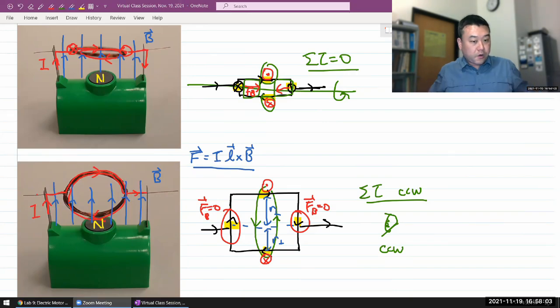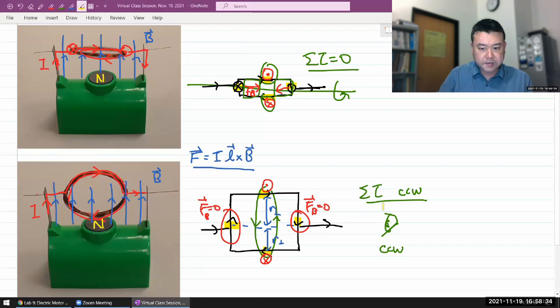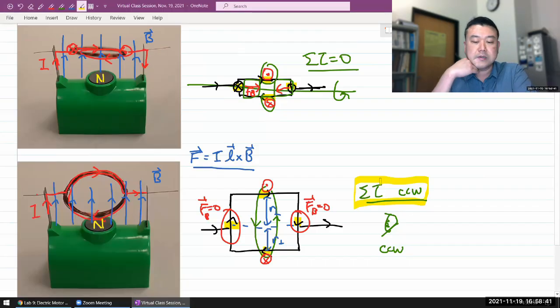So that's the motor. Now, as you are hearing this description, if you are asking yourself the question, so why didn't we do this earlier? Well, yeah, you're right. We could have done this earlier. And here is why we are now talking about the motor. Because if we had talked about the motor before this week, there's one aspect that we couldn't fully explain, which is this. As you imagine this setup, this net torque being exerted on the coil of wire, you have this torque whenever the wire is in this orientation, and there's nothing that says that as this thing spins faster and faster, torque should be less.